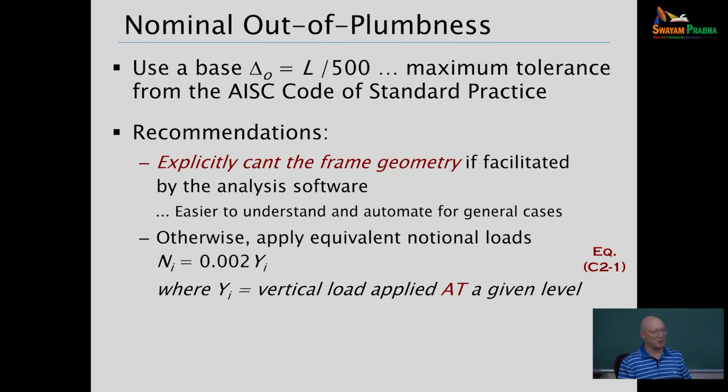If you're using notional lateral loads, you're using something that's equivalent to that, and it can be a little bit difficult in some frame configurations to understand what those notional lateral loads are. If you've got, say, a gable portal frame with a lean-to or with a mezzanine on the inside of it, and some geometries are not perfectly rectangular, you start scratching your head about, well, what are my notional lateral loads here?